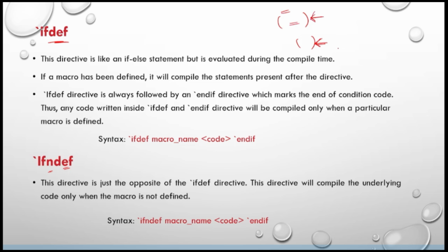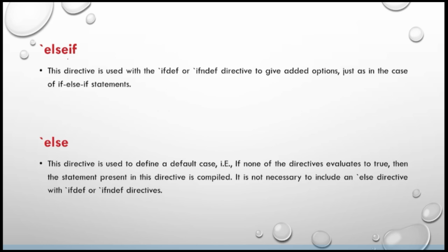Okay, so basically in such conditions you will be using `ifdef` and `ifndef`. Similar to this, also `elsif`. It is very similar to conditional statements like if, else if. Okay, you already know the conditional statements. Similarly, you will be using these compiler directives like `ifdef`, `ifndef`, `elsif` and `else`.